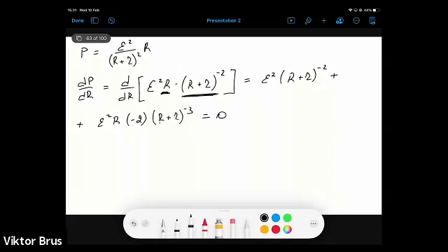So in order to proceed further, let us multiply and divide the first term by R plus r, load resistor plus internal resistor. So let us write it here. We can write epsilon square divided by (R plus r) squared.